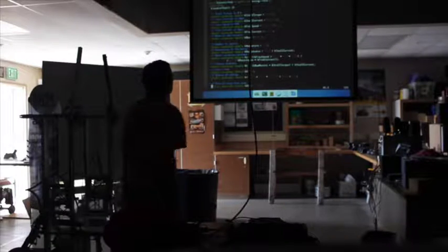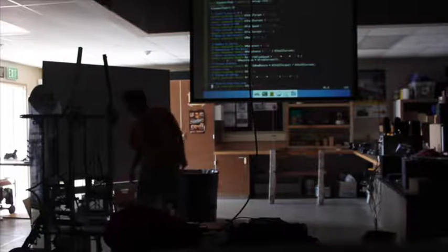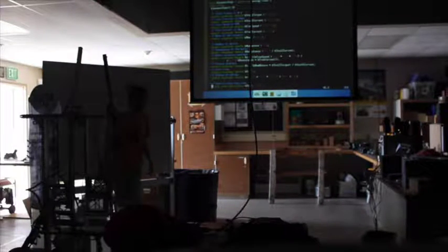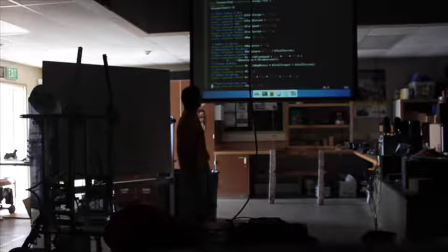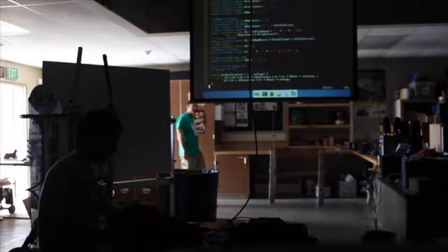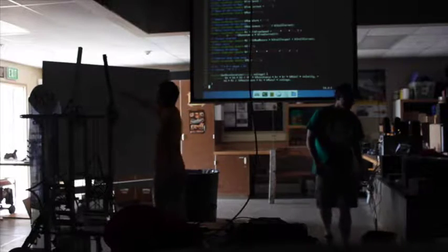So this is the skeleton for our test case. I took the liberty of figuring out all the physics constants. It has a mini sim on it. So I grabbed the stall torque for the mini sim, stall current, free speed, free current, and estimated a mass for the elevator. We pull out, just like we did last night, our voltage constant, our torque constant, our gear ratio, and computed a pulley radius. And if we plug that into our equation from last night up here, we can compute an acceleration. So I typed that all up.